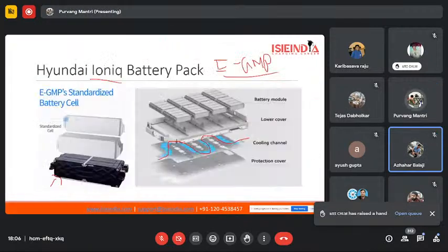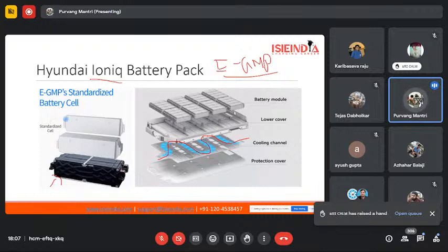Yeah, pouch cell. So in pouch cell, each pouch is flexible in nature, and that's why you can house multiple pouches in one module. And they have developed their cells in such a way that they can be efficiently cooled. I still don't understand why they are not going for the cylindrical cell, but I'm still getting deeper into this subject as well. I'm trying to find answers for the same question that you have asked right now. But coming to the mechanical abuse point, they actually have structural rigidity provided in the chassis as well to prevent these battery packs from having mechanical penetration within them.